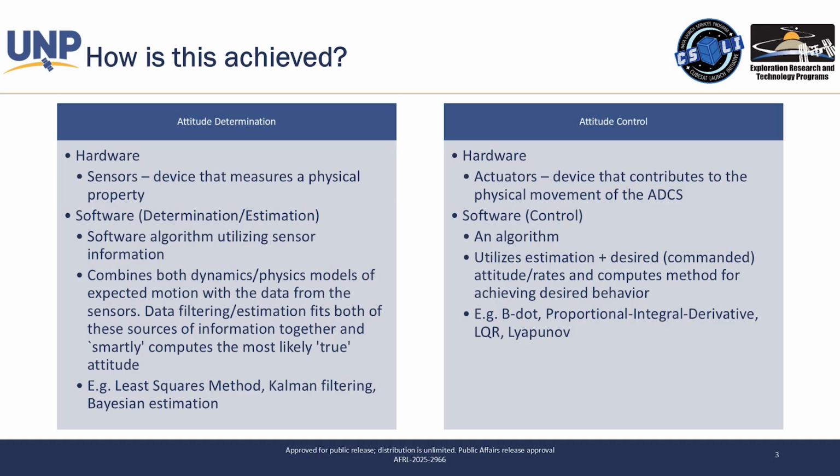Attitude control then, right? Actuators, these are things that maybe reaction wheels or whatnot, but we also use software then, which is essentially our controller, and it uses the estimated attitude as well as the user input, you or I, where do we want to be looking or pointed, or how fast should we slew? And then it controls your spacecraft to get you there. And you're usually looking at your rates. That helps you a lot.